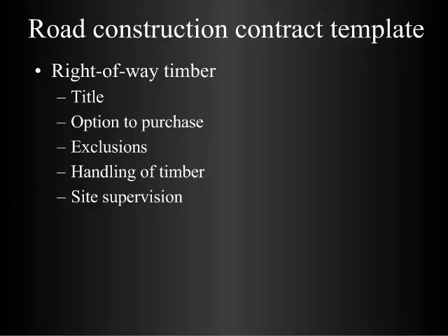Site supervision, this one's a big one actually. You can get a lot of promises about whoever you've made your contract with being there all the time to supervise it, but it doesn't always happen that way. You'll go out and find people that really don't have that much skill or knowledge out there performing tasks, and it will make you a little nervous. So it's good to require that they have a designated supervisor that's approved by you, the landowner, on site at all times.